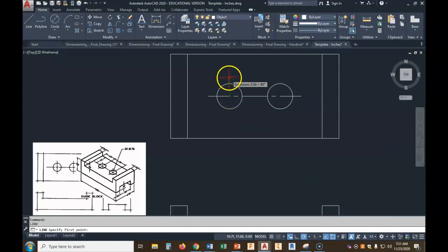So let's go back in and try it again. Okay, let's get this quadrant. Now let's drag up, okay? Right there, 0.25. Okay, so let's try that now. I'm going to go to line, hover here, and drag up, and say start that up above it, 0.25. See, there's that point, okay? Notice I didn't click here, I just hovered.